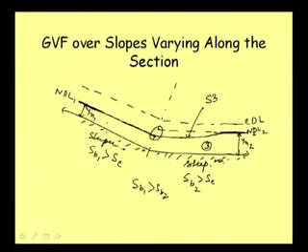So to compute this profile, knowing the discharge Q, the channel shape and the roughness, we can compute this particular depth, and then knowing this depth we can start our computation from this point, where x is equal to 0, suppose, and y is equal to yn1. Then we start computing in the downstream direction, and we can go up to the point when y is just less than or equal to yn2. Well, so this way we can compute.